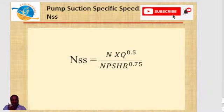All right, so it's also very important for you to calculate and check the pump suction specific speed, because it is a function of your NPSHR. The lower your NPSHR, you can see the higher will be your pump suction specific speed. All right, so the NSS, which is the pump suction specific speed, is expressed by N multiplied by Q raised to the power 0.5 over NPSHR to the power 0.75.